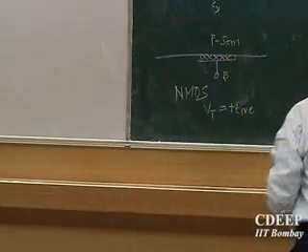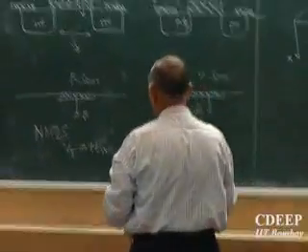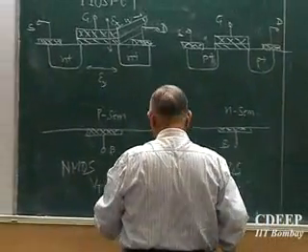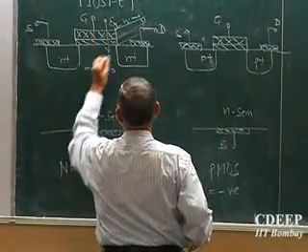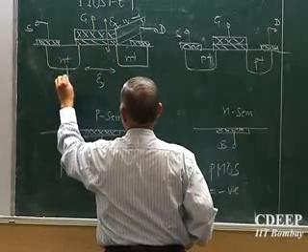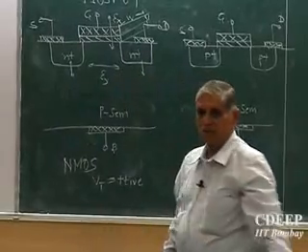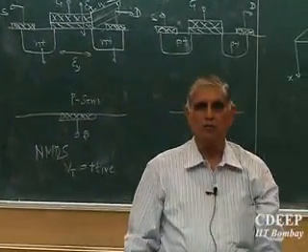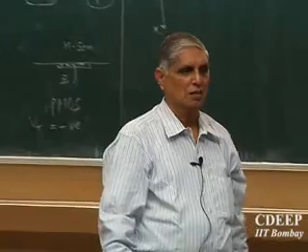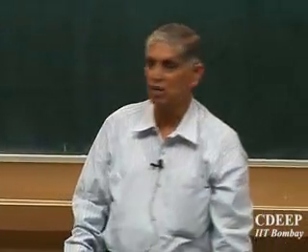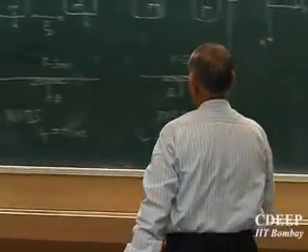But if you see here, I also keep seeing junctions. It's not only the MOS capacitor which I am seeing here, but there is, what is this? There is a PN junction, one from the source side to the substrate, the other from the drain side to the substrate. So essentially this has two diodes.